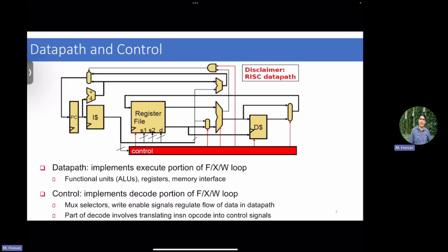Good. So if I'm building the machinery, the circuit that tries to implement the ISA in a non-optimized format, what do I need? Well, we talked a lot about a program counter. That is a register that holds the address to get the instruction from the memory. Which is the very first part of the control path. I need to bring in this instruction from the memory to the actual processor execution, right? So the program counter is the first thing you will encounter here.